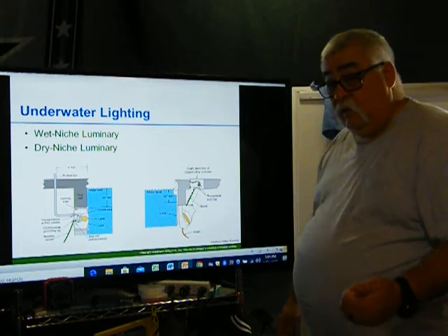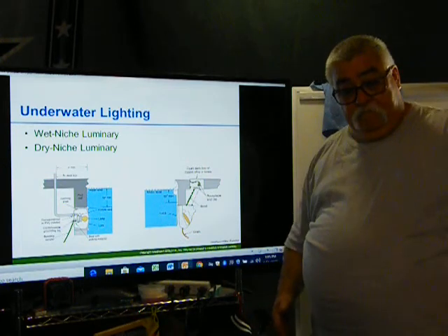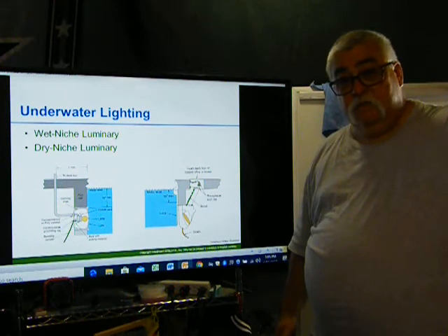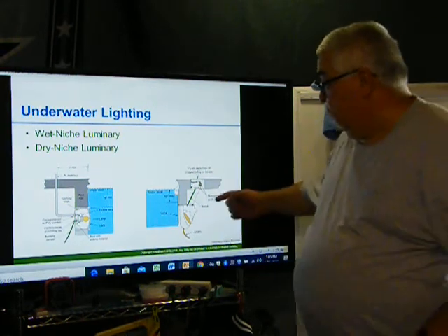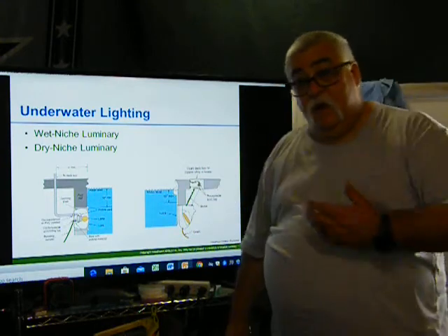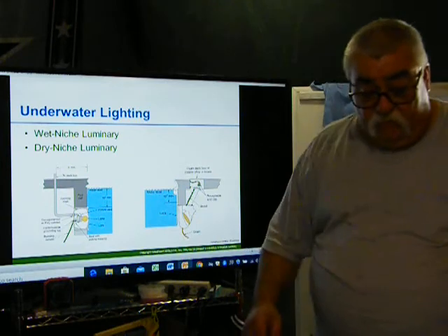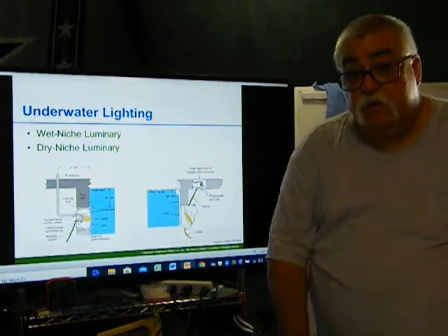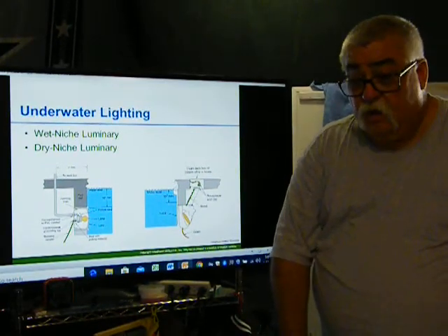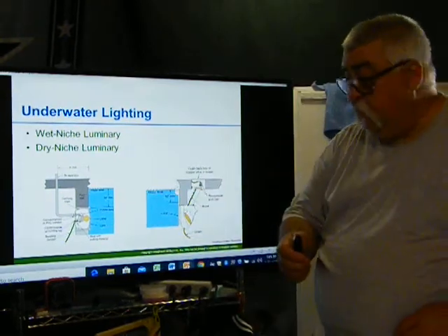That's why they required us to put the boxes so high out of the ground, so the water level did not come up and fill this gap where now it's within the water. So that is one of the very important things that some areas do. Remember the code, this is a minimum. The code allows these deck boxes.